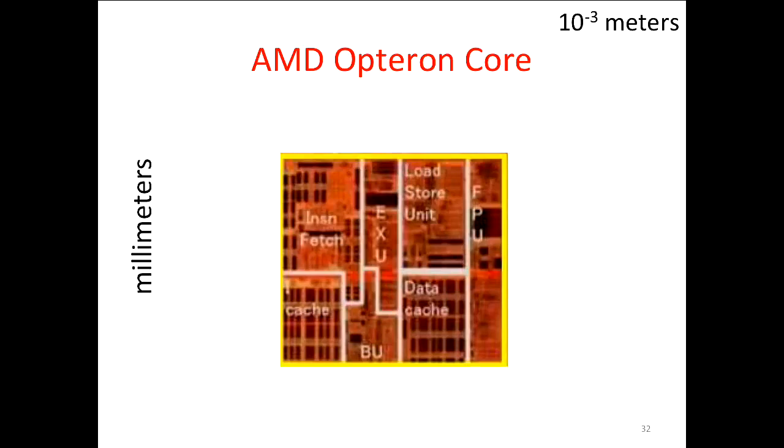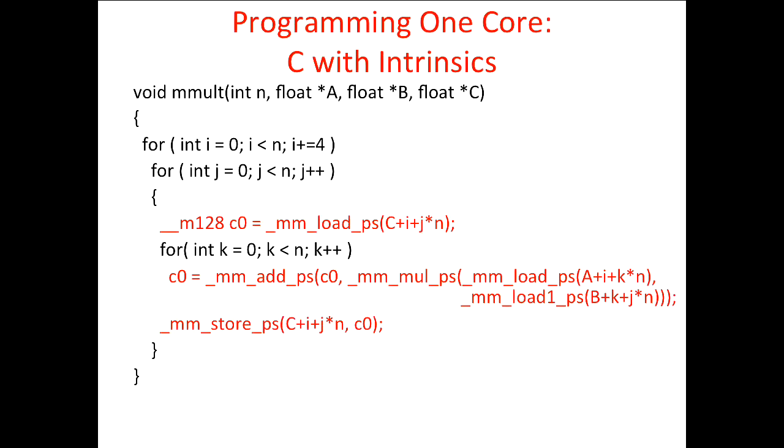Here's the load store unit, instruction fetch. Here's the iCache. So basically instructions flow from the instruction cache into the instruction fetch unit, into the execution units. The load store unit touches the data cache, and instructions go to the floating point unit, right?